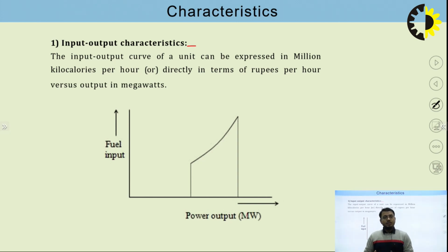That superheated steam is injected over the turbine, which rotates the turbine, connected to the rotor of the generator by a shaft. Both rotate at the same speed, and as the rotor rotates, it cuts the flux. By Faraday's law of electromagnetic induction, the generator generates electricity. So this is how power is generated from a thermal power plant, right?